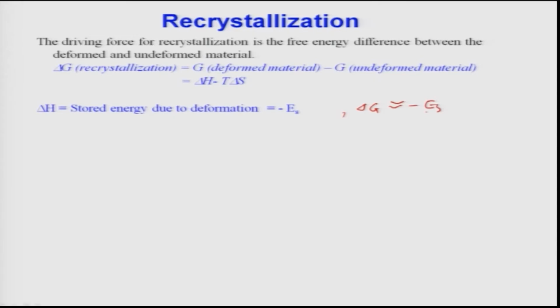Second important aspect, the rate of recrystallization. The rate of recrystallization is given by this formula. As you have seen, N dot is given by N nu times an exponential function, minus 16 pi gamma cubed, where gamma is the interfacial energy, over the V squared term.